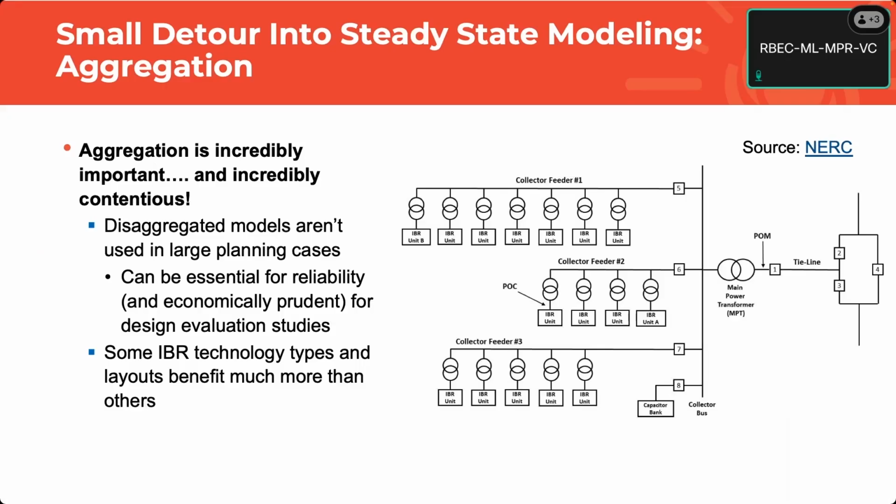So a lot of the time it's a good idea to do a disaggregated design evaluation study in the positive sequence domain or in the steady state domain. I'm not going to recommend a full detailed or disaggregated model in EMT right now, because not everyone has supercomputers for that, but it is possible.